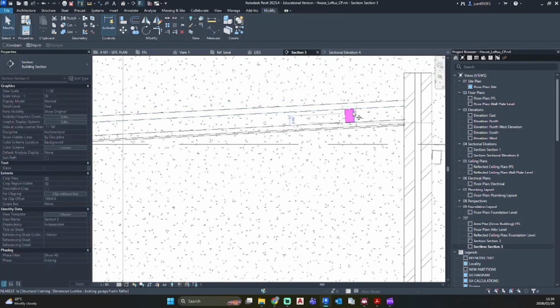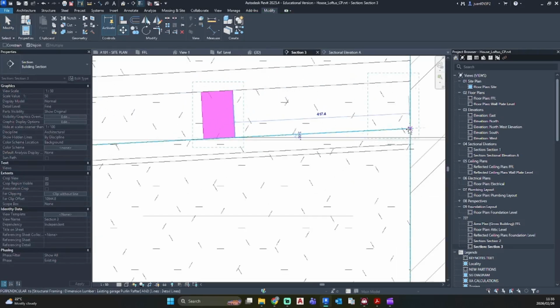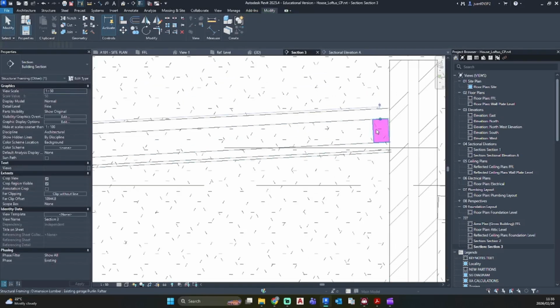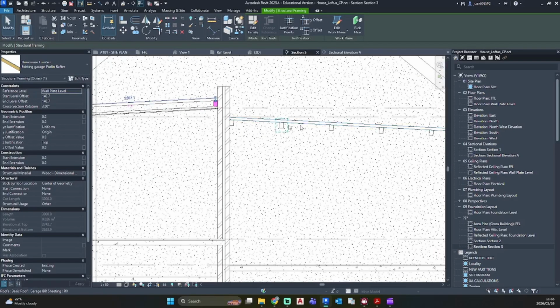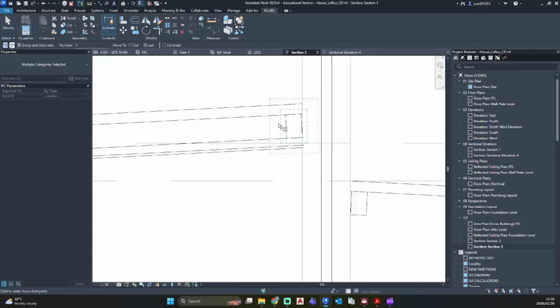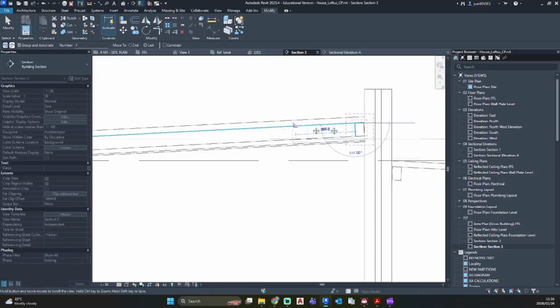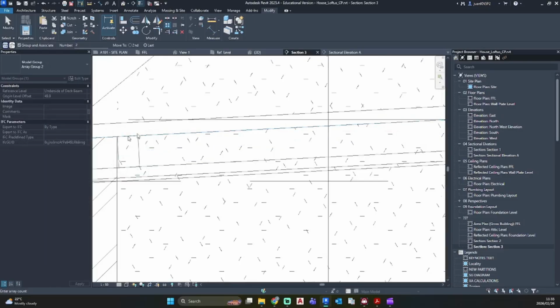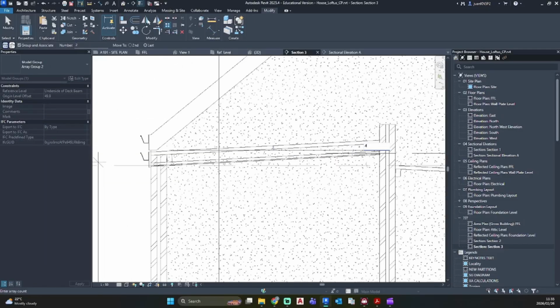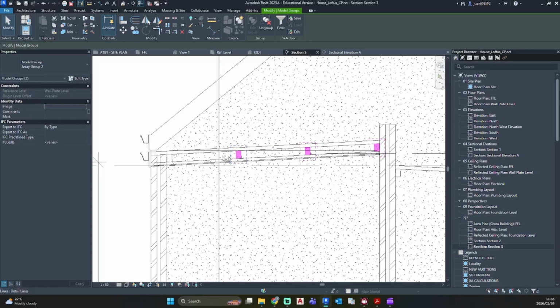So now I'm going to move this and put it in there and use the same like we did here. Go AR for array, we want the last one, and if we check our section, there is 4 of them. So that one, and we need to enter 4. And there we have, I'm just going to ungroup them.